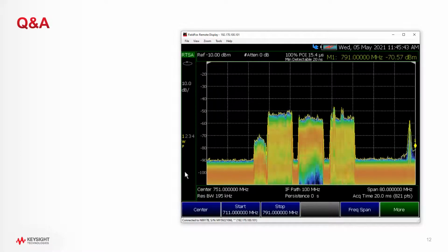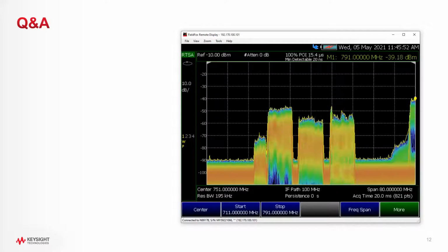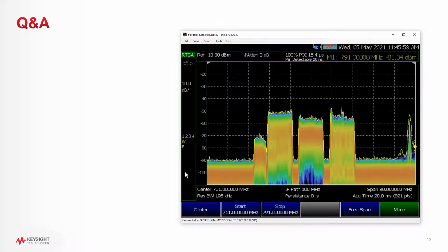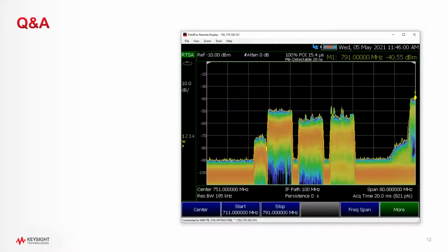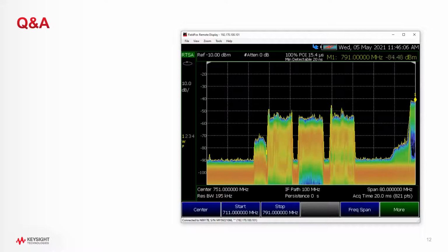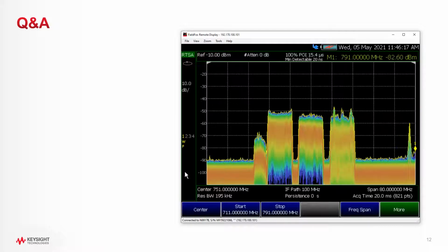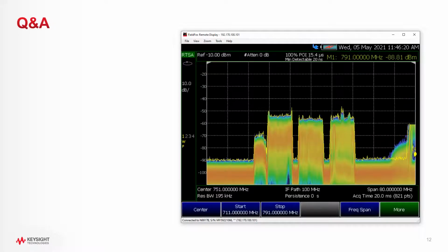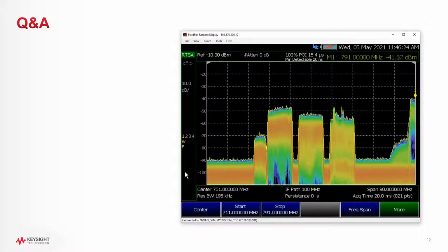Bad devices. A lot of times there can be devices that are supposed to be following the rules, but they're defective or broken, and so they start creating interfering signals. Bluetooth is pretty robust though, because it does hop. So it becomes more of a fringe issue usually, that you're within the range that Bluetooth should work. There's 30 feet, there's 100 feet, there's 300 feet, there are different specs. But when you get to the edges, there's just too much noise for you to get the signal through because there's too many devices or too much Wi-Fi in the area. So there's not often you can do anything about it.